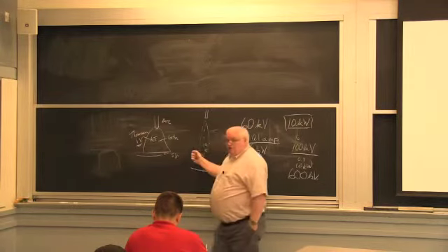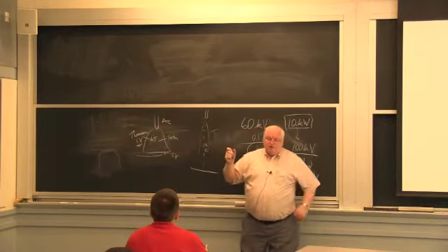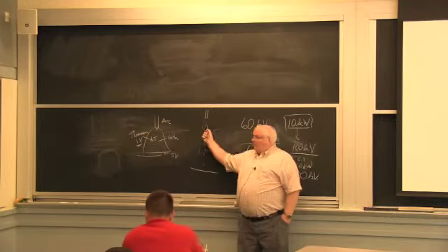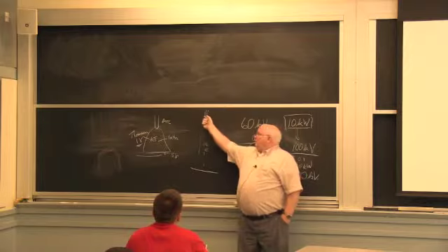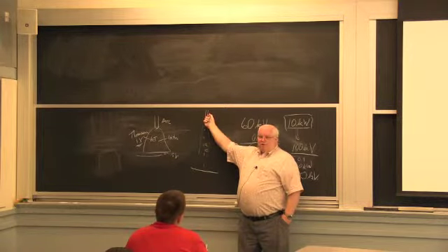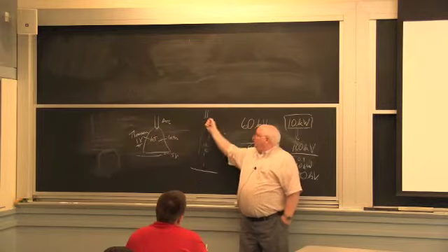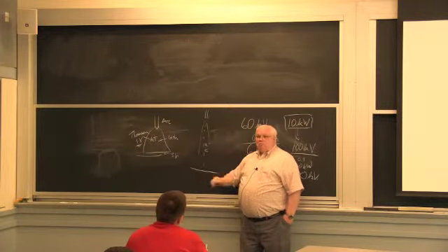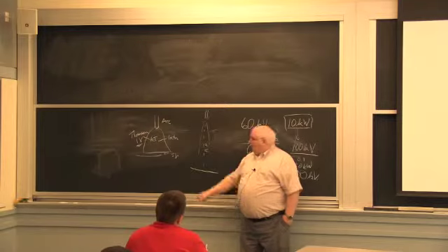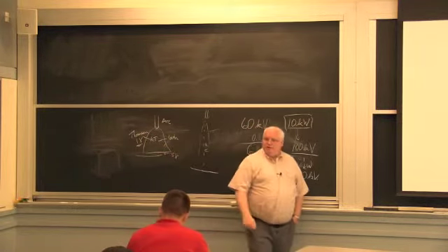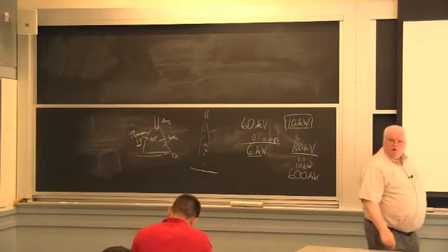So it's a very energy efficient process. Calculations show it's 99% energy efficient. The wall plug power in your beam, wall plug being from the gun up here, which is a hot tungsten filament in a vacuum, and you're just boiling off electrons in a big electric field. That wall plug power from that electrode to here is near 100% efficient. In an arc, it's 50% because it has all these hot gases going off to the side, wasting energy, just heating up the guy doing the welding.